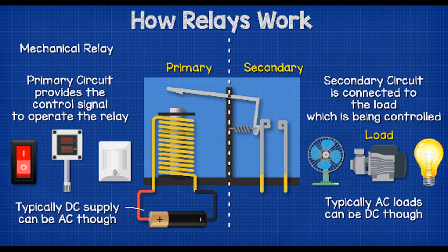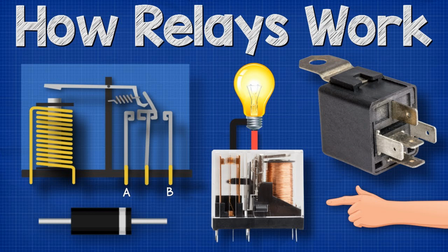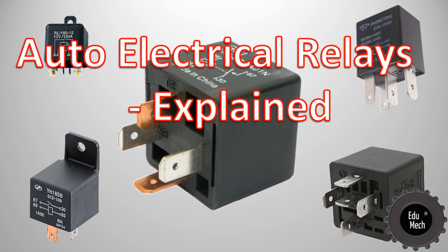Advantages. Flexibility: allows for timed operations in control circuits, enhancing automation and system efficiency. Energy efficiency: can prevent unnecessary power usage by controlling devices based on time delays. Simple integration: easily incorporated into existing systems without major modifications. Disadvantages. Mechanical components: if using mechanical timers, there may be wear and tear over time, leading to reduced reliability. Accuracy: some older designs or mechanical types may have less precision in timing than electronic or digital alternatives.